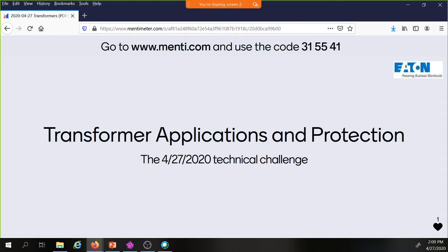So I'm going to look at the chat session. I'm going to look actually on YouTube. What are the questions there? I love the fact that you guys are chatting away. It's my proposal to flip. I saw that. I understood that you can use six disconnect rule on the secondary as long as the total rating of the breakers does not exceed 125% of the full load current.